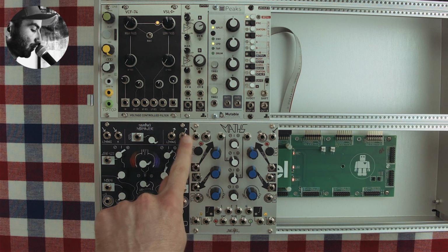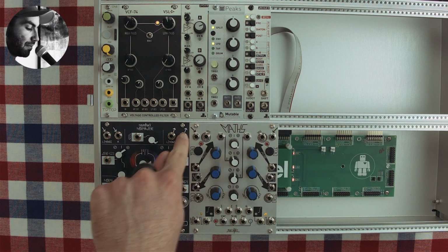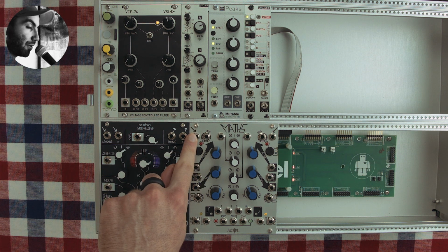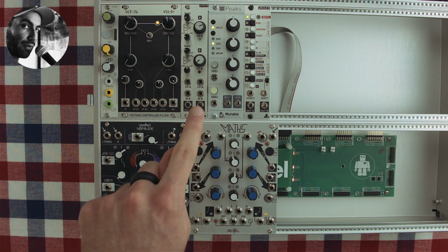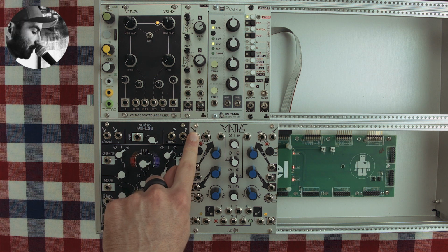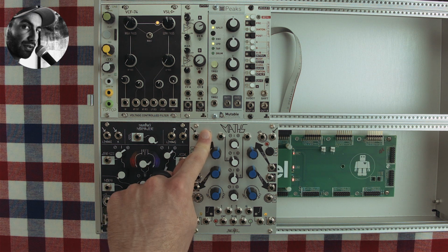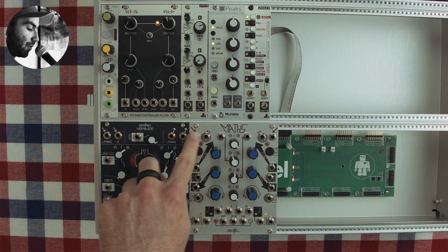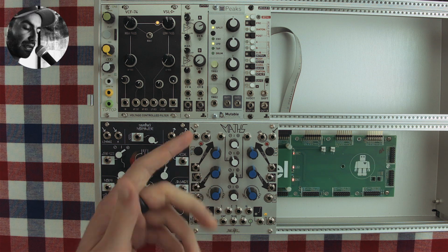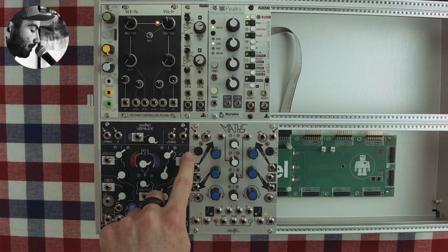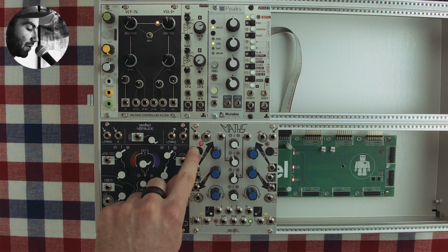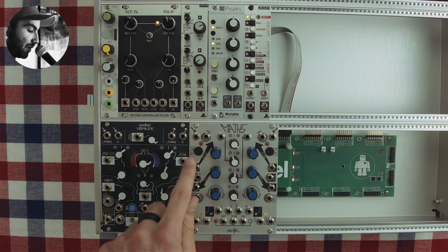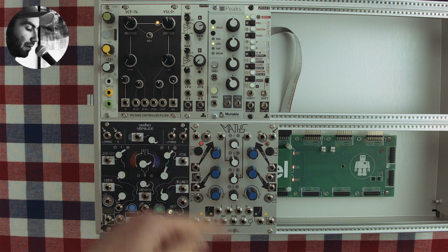Starting with channel 1, at the top we have various kinds of inputs. For channel 1, we have 2 inputs. We have a signal input, which you can feed an audio signal or a control voltage signal. Then we have a trigger input, which you can feed a normal trigger signal into. These are different ways of triggering and creating the function. Below that, we have a cycle button, which you can toggle on and off. That just turns it into an LFO effectively. When you turn on cycle, the function will keep on looping.